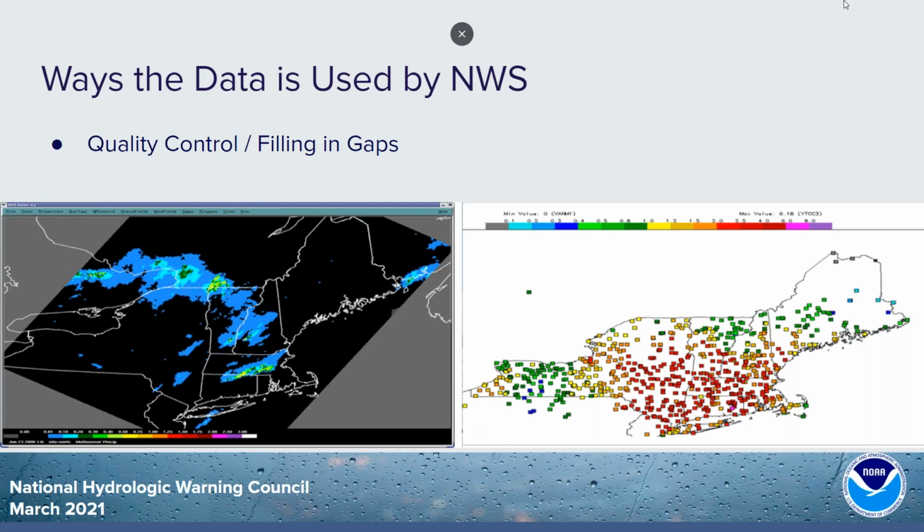The flood warning system data also might fill in gaps between existing rain gauges, like is shown here on the right. Density and redundancy aren't necessarily a bad thing either, even if it doesn't fill in a gap. If you have 2 gauges, as far as I'm concerned, that are on the same street, half a mile apart, they're not necessarily going to have the same values, and one of them might get clogged up and the other one might be fine. So I don't think there's ever too much data, especially if it's kept in good condition.